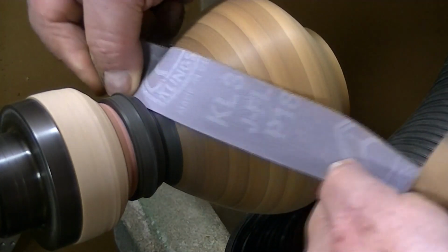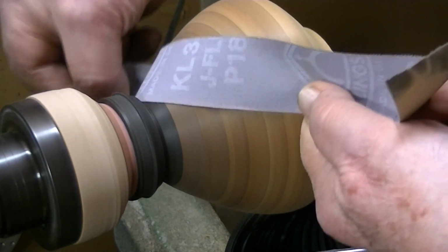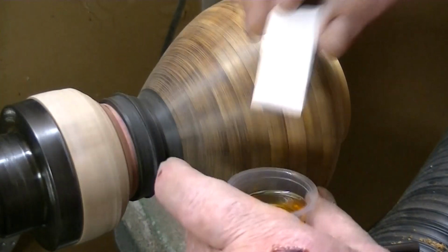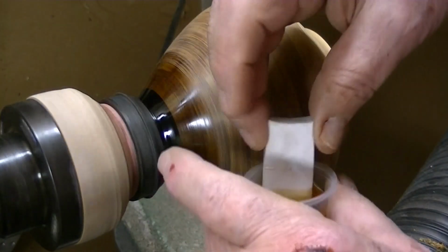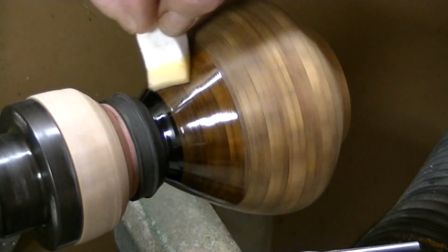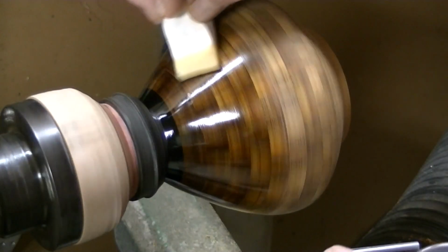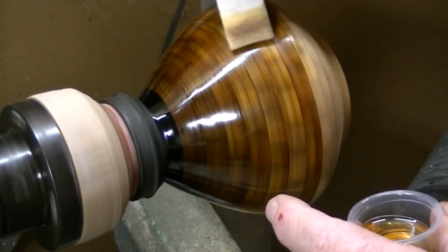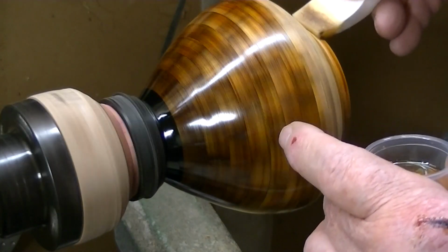Once that's been shaped properly, a little sanding here to finish up that area also. So we've got it done. Now it's time to see it really begin to pop. So I've turned the speed way down, and I'm going to apply a little of my Minwax wipe-on poly, the clear coat. And the first coat goes on fairly heavy because a lot of it will soak into the wood grain, acting as a sanding sealer, or a sealer in general. And as it dries, I'll go back and go over it again. So I'm putting on a fairly heavy coat.